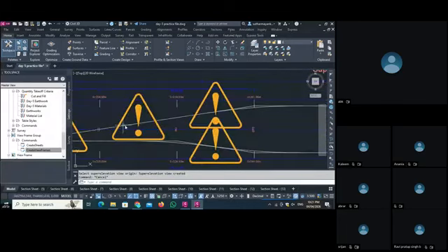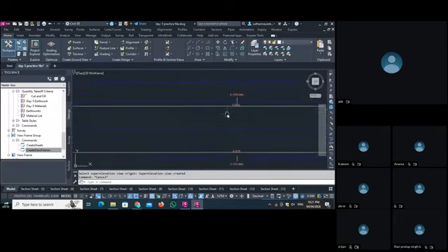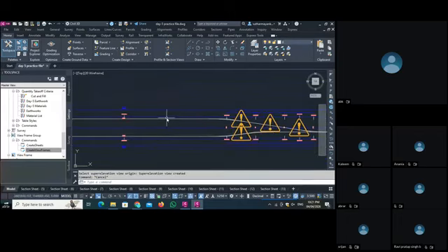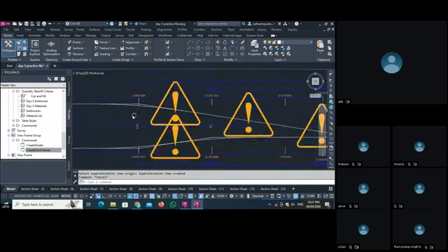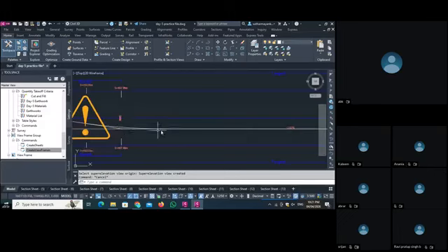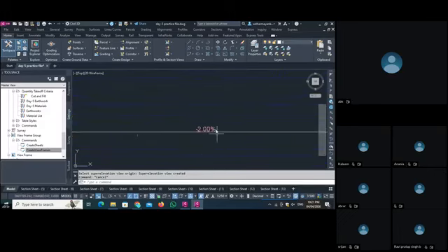In a curve, you have the slope as 4%, super elevation is 4%. Generally, as per theory, it will take till 6%, but in practical, we will take till 4% only. 3 to 4% is manageable. Then again, the curve joins with our existing alignment, and 2% slope is there.